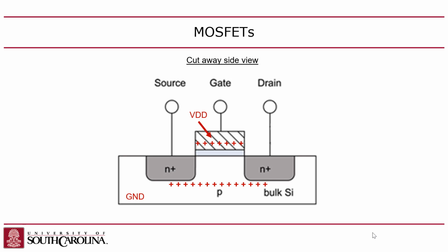But after you start accumulating charge there, you get the minority charge carriers in the channel, which decouples the channel from the substrate, and so the voltage of the channel is no longer ground. The voltage of the channel is now an average of the source and drain, because there's a connection there. So it becomes a little less straightforward to calculate the gate-channel voltage.